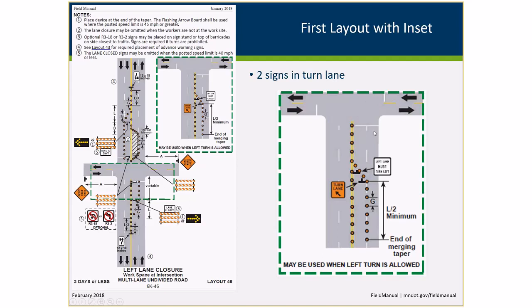Maybe someone's turning right here and they don't want to have to wait for them, and so they get in this lane and then they try to merge up in this area, and then you can have a merging conflict occur within the intersection itself. So this makes it regulatory that they have to make a left turn from that lane. So once they're in the lane, they have to turn left. This lets them know to go into that lane to make that left turn.